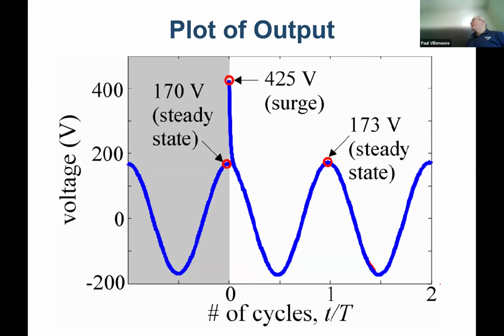Yeah, so the question is, do all parts of the system have the Zener on it so that they will be protected? They may. It depends on how much effort the utility has put into protecting their system. So they're obligated to provide nominal voltage plus or minus 5%, but they don't claim that there won't be switching transients that would cause an issue to loads, because it's not that common. But if you're out on the system and you have some very sensitive equipment, then you would be obligated to do it on yourself.